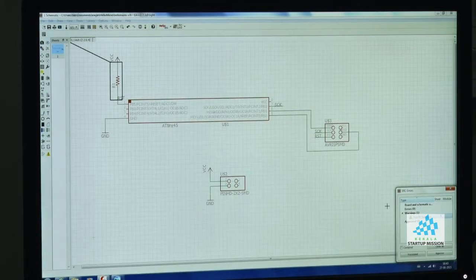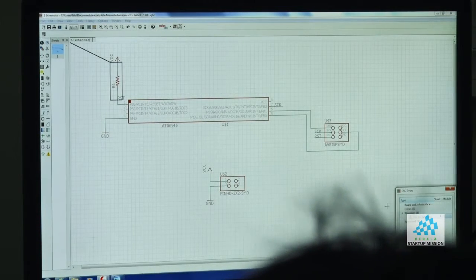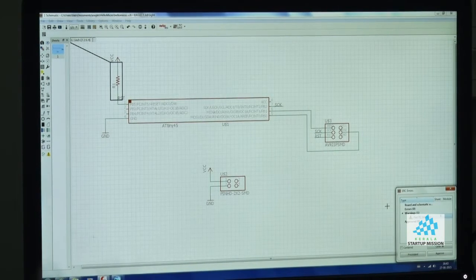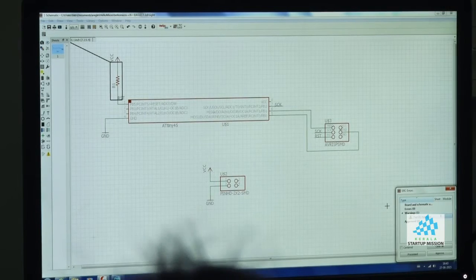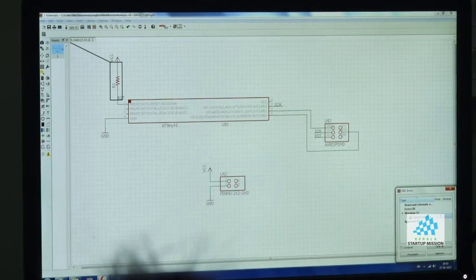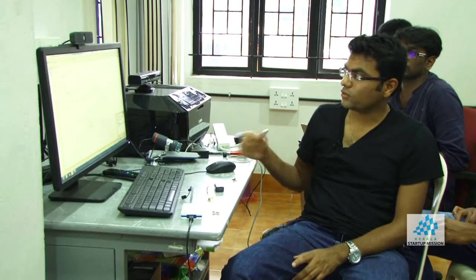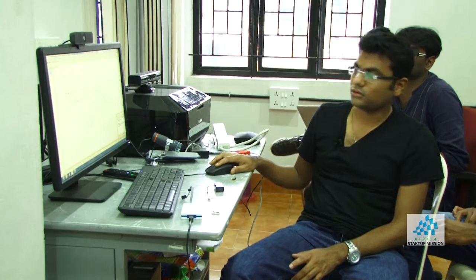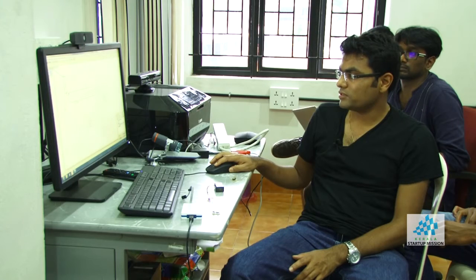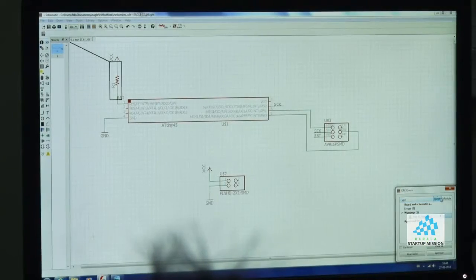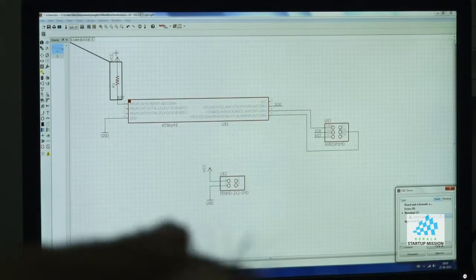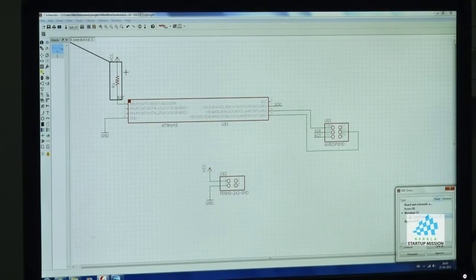So what happens during schematic is there are 2 options. One is sometimes you put circuit tracks so close that they cannot be milled. So for that you can do something called a design rule check. The design rule check will tell you if there's a problem. And for the electrical circuit check, you can do ERC, which is going to tell you. For example, it is telling me right now that my resistor is not connected here. So probably I didn't connect it properly. So that I'm going to fix.